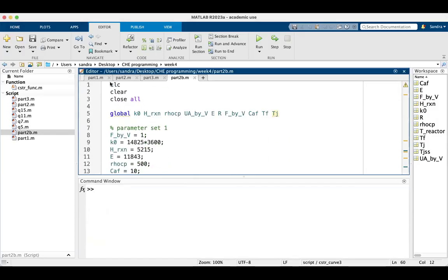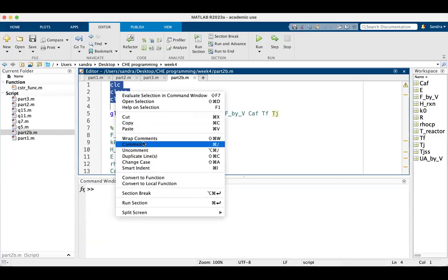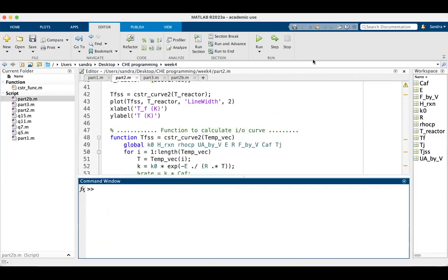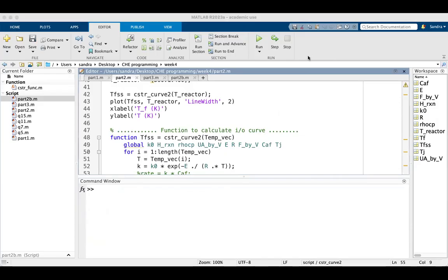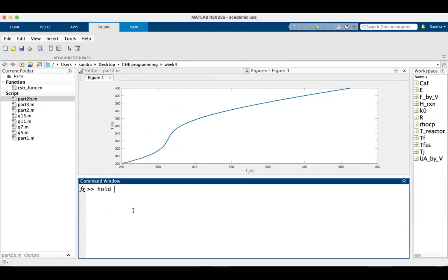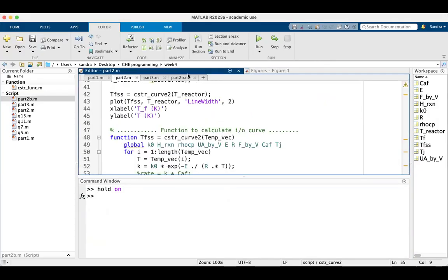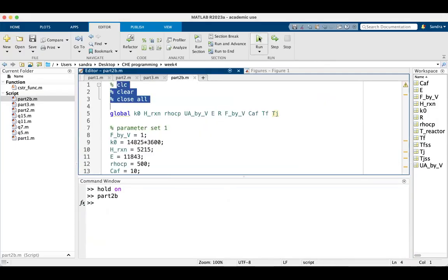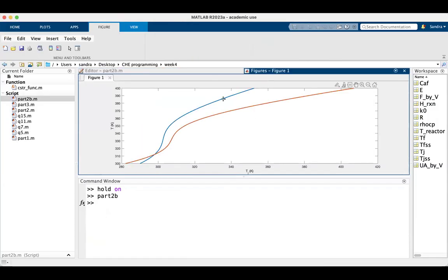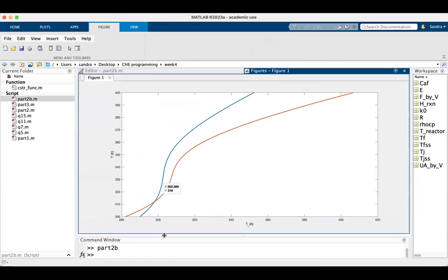Basically what happened is, you have two behaviors. The first one, what I did was for the feed temperature, and the next one is for the jacket temperatures. It has still been increasing, so it will still take time for it to reach the steady state.